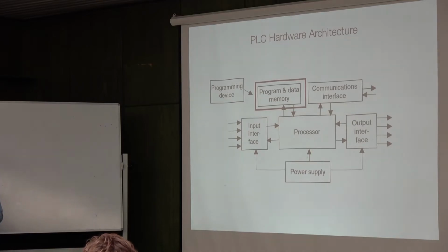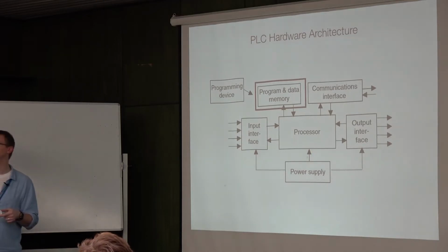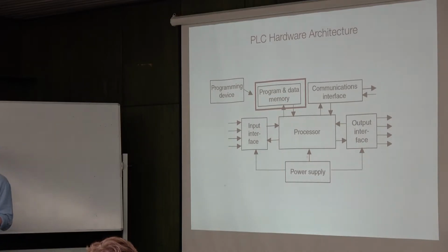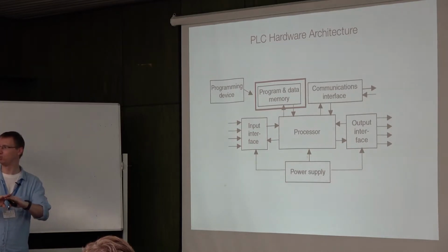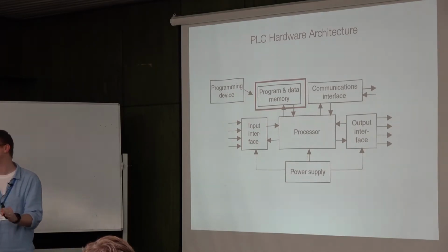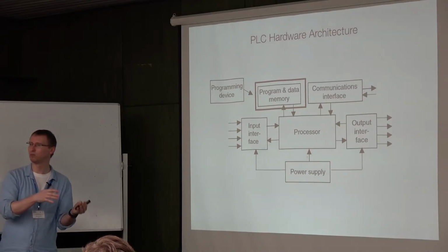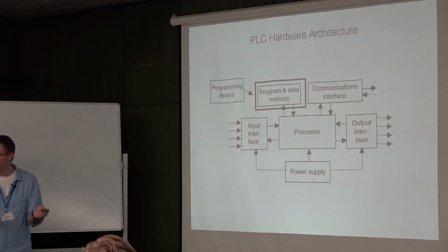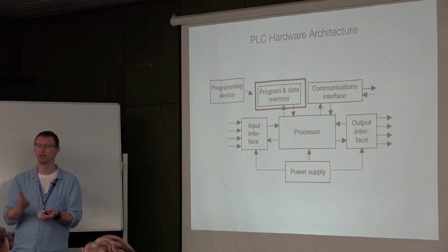These kinds of things. In PLC, it's usually even worse. You have to even specify the location in the memory where you want to store that variable. And it's up to you to make sure that 2 variables do not overlap in the memory. Of course, there are some advanced PLCs which do this memory allocation for you automatically. But again, I just want to show you the common denominator. And then the standard practice is we do even the stupid memory allocation manually.